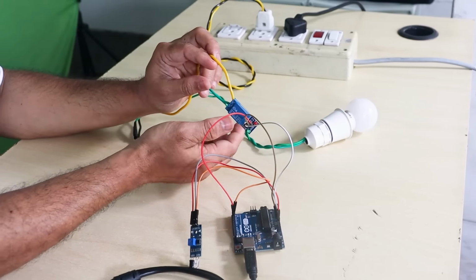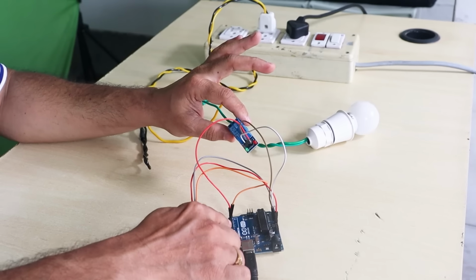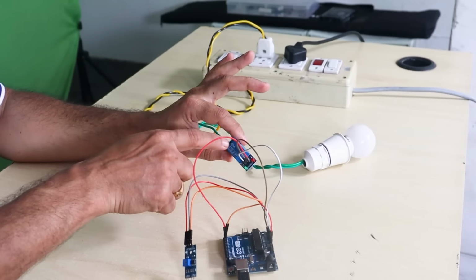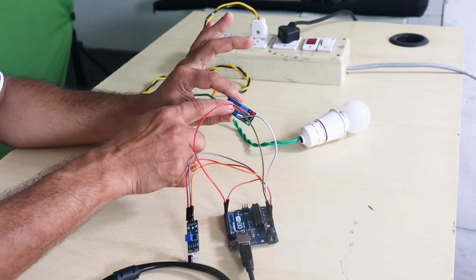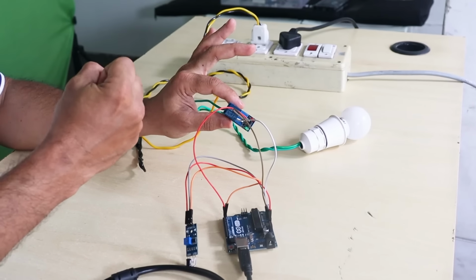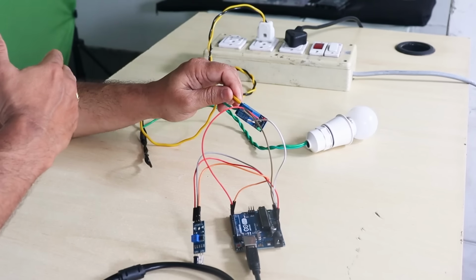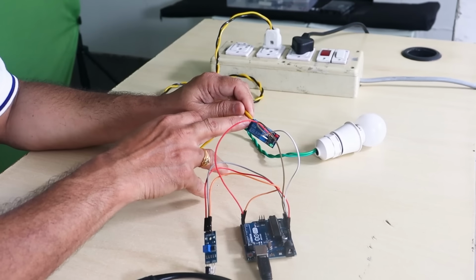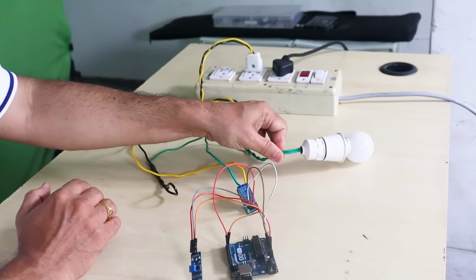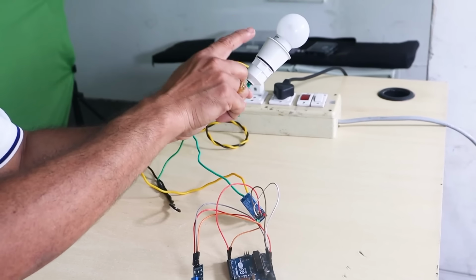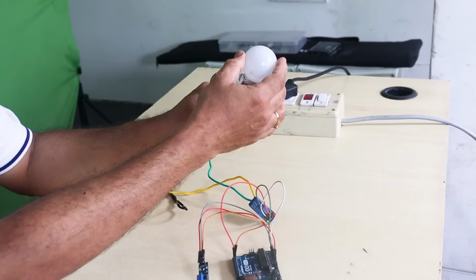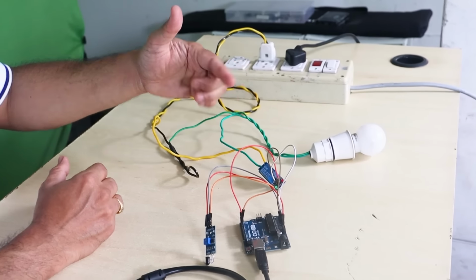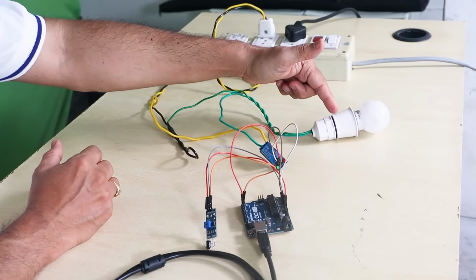So that way, whenever the command is sent from the Arduino board to the relay at VIN, the magnetic coil inside the relay gets energized, and that is how it will switch the state from normally open to common. So when it is switching the state, the circuit gets closed for the bulb, and that is how our bulb starts glowing. Right now it is in the open state, it is broken open. Until I send the command, the bulb will not glow.